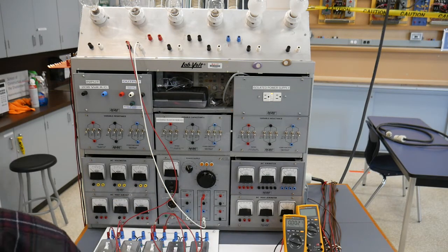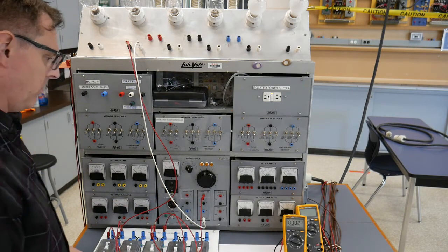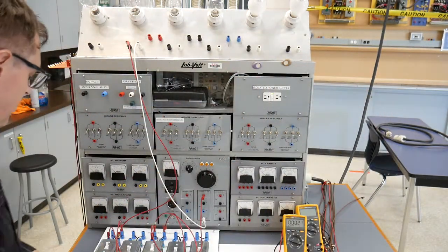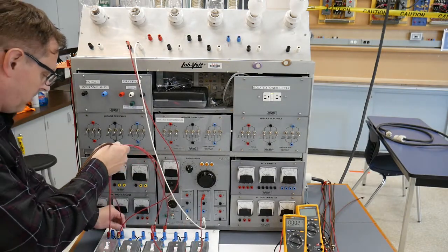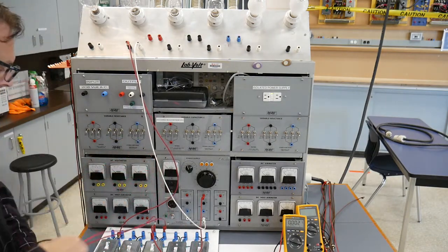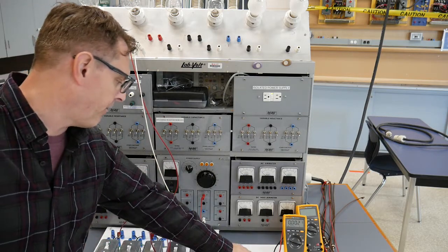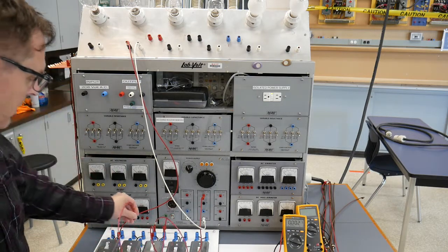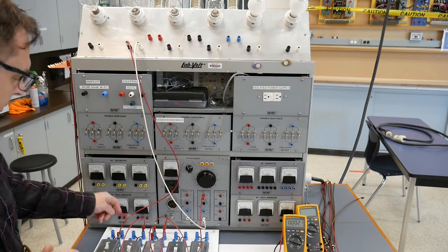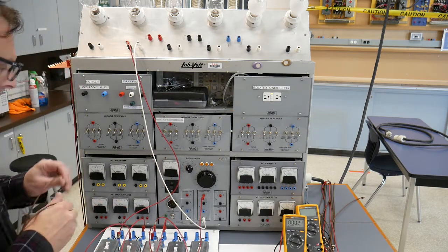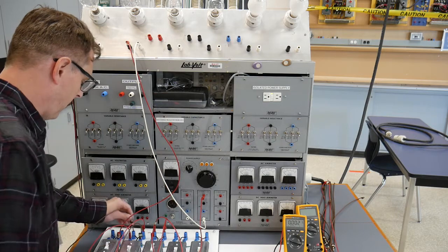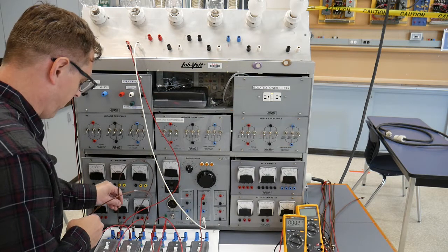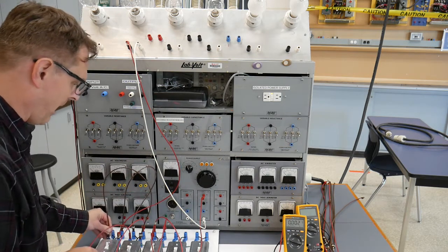Okay, no metering required here either. All we're going to do is require 2 more wires for my other set of travelers. I'm just going to unplug these travelers from this guy. Okay, and now we have to look at how that 4-way switch was working. I've got it labeled so that the input was the top right and the bottom left. And then my outputs were the bottom right and the top left. And they need to go over to the other traveler terminals on the other 3-way. Everything else I've left intact because it stays the same.